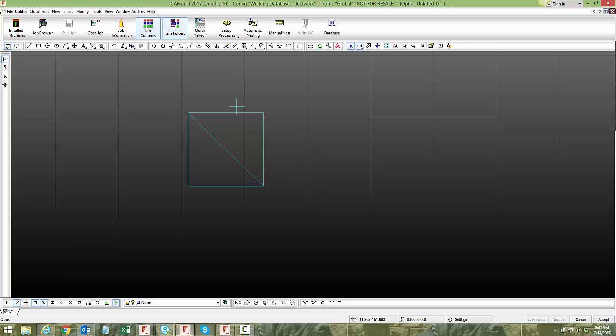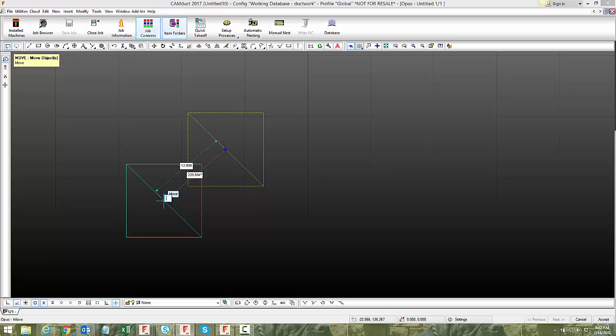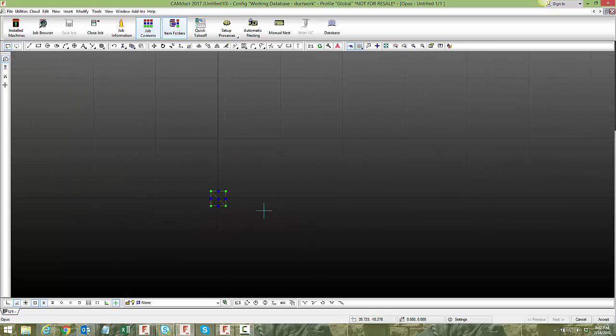Now your steps here. If you were to just save this right now, when you place it inside of your CAD program using DesignLine or EST, it's going to throw it out in space. So what I always do is I move this from the center point to 0, 0, 0. Once it's at 0, 0, 0, we're now ready to save that.